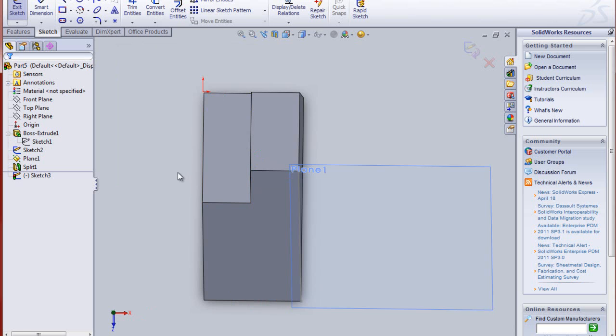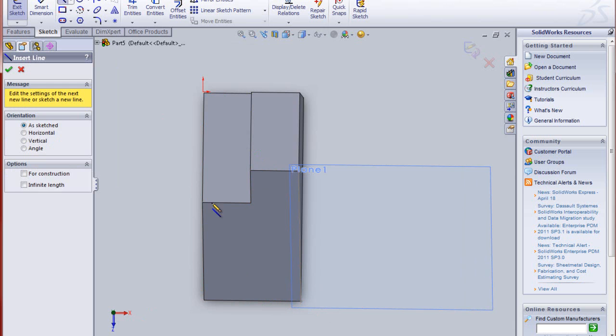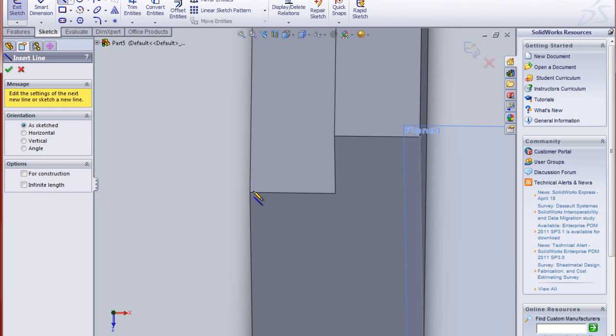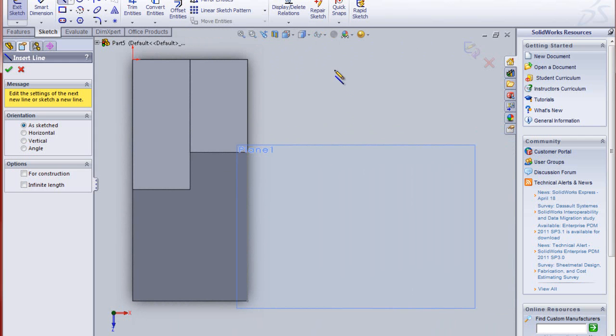And if we look at this drawing, from this point to this line that is 45 millimeters from this edge is the line we want to create. So I'm going to create a line. I'm going to see if we can snap to this point, and if it's not there we may have to project the geometry. Let's take a look here. Rotate it a little bit better. There we go. I did normal.